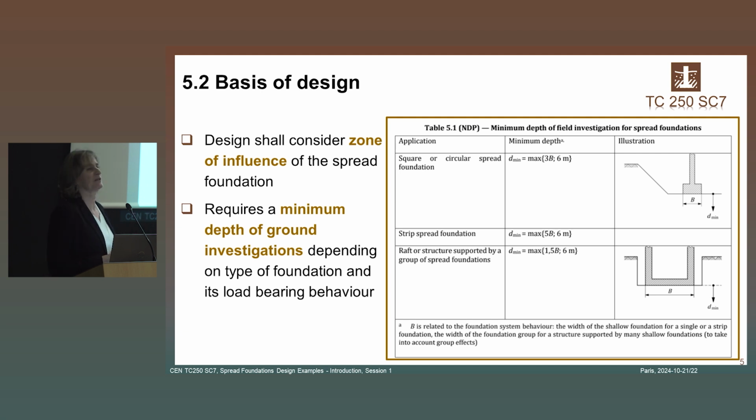So here for the spread foundation in subclause 2, and here in table 5.1 you can see the minimum depth, and it depends on the type of the spread foundation and its load transfer zone, let's say.